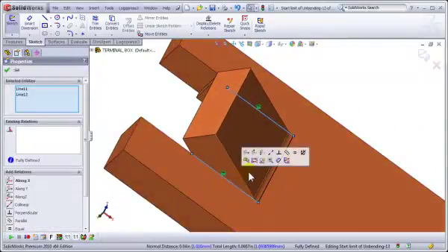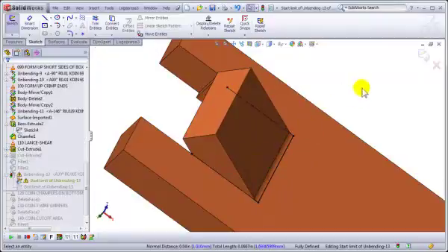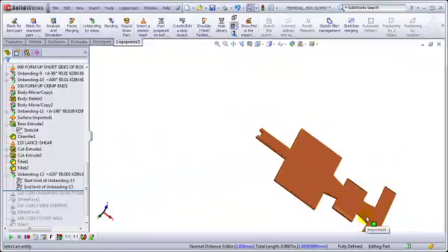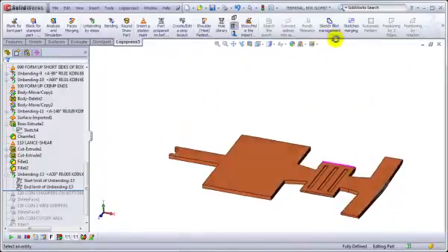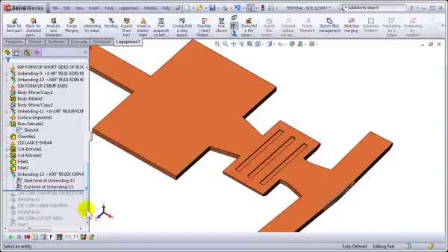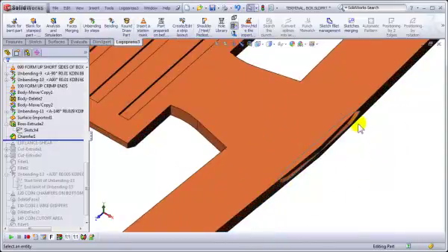And we'll set these to construction as they were, so we won't have any errors anymore. And then actually we need to roll back up here, because I believe, yeah, this is where we need to cut out this extrude. Or not the extrude, we need to cut the chamfer here.